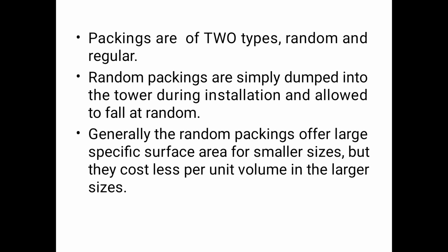The packings are of two types: one is random packing and the other is regular packing. Random packing means it is simply dumped into the tower during installation and allowed to fall at random. The packing materials are simply dumped into the distillation column. There is no arrangement of the packings during installation.